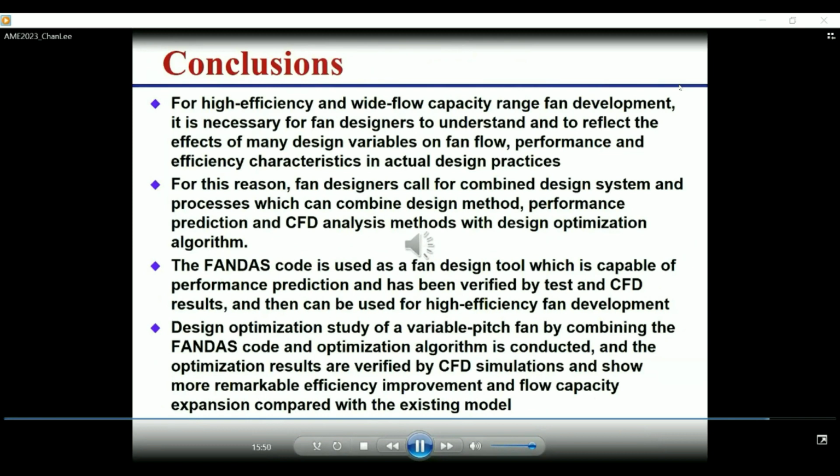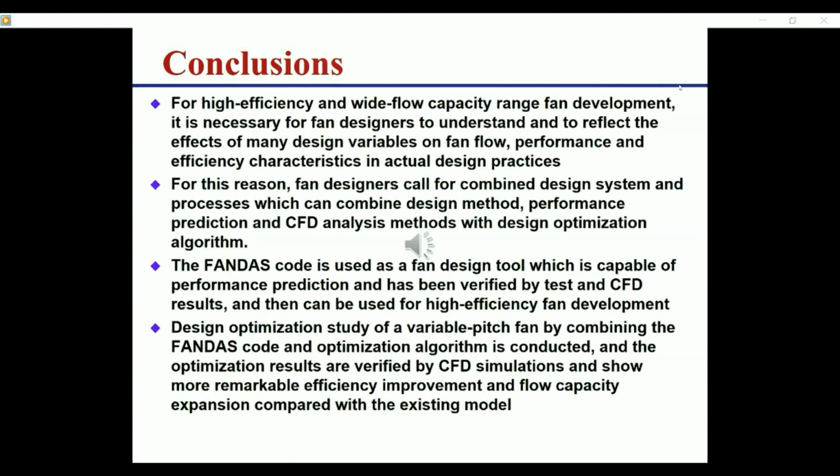Finally, let me make conclusions. For high efficiency and wide flow capacity range fan development, it is necessary to develop and apply a computerized development system which can combine design method, performance prediction method, and CFD analysis method with design optimization algorithm.